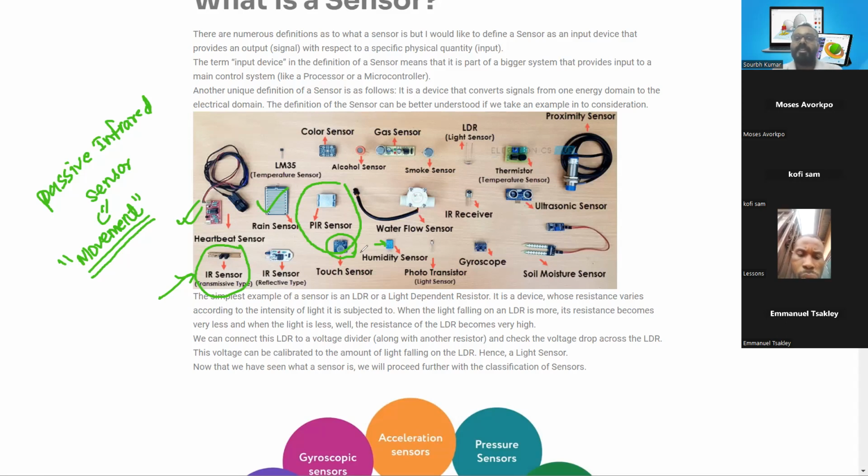If humidity exceeds a certain limit, then bacteria will start propagating into the food, and it will damage the food grains and the seeds stored in a storage rack. So we can utilize the humidity sensor to detect the exact humidity, and we can further reduce the humidity using a heater system. We will execute that task using the humidity sensor plus a microcontroller, and further the heater as the output for that particular situation.